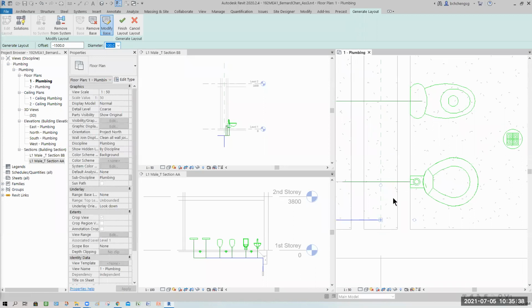Because if I give the pipe size 150, this is 100. You see the connection, and these two have to join together. That means they need to have 150, 150, or those fittings. Then it would be a nightmare. So here will change. But meantime, what we want is only 100. So please do it properly, and you'll see that it's going down now.